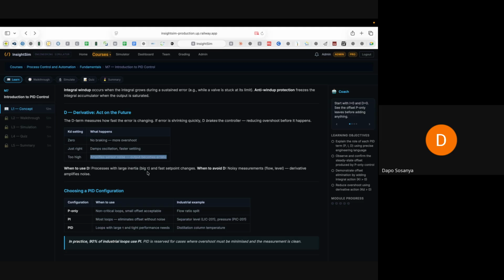Who remembers? Okay. Time constant. Tau is a time constant, the process time constant, right? So, processes with large inertia and fast set point changes. So when to avoid D? When you have noisy measurements, right?